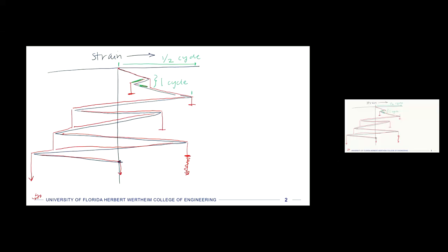So what we're looking for are the ranges of things that go fully one way and back the other way, fully up and down. Okay, so if we keep going, our next rainflow starts at this location and goes down all the way to the end here, where we have that arrow. So it spans basically the highest positive strain all the way down to the lowest compressive, lowest negative strain.